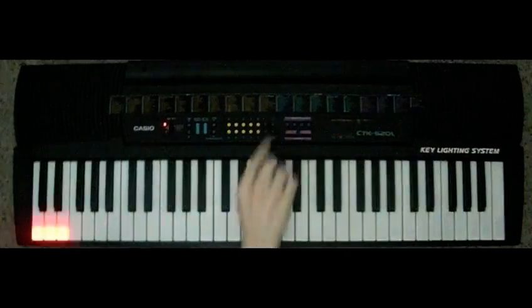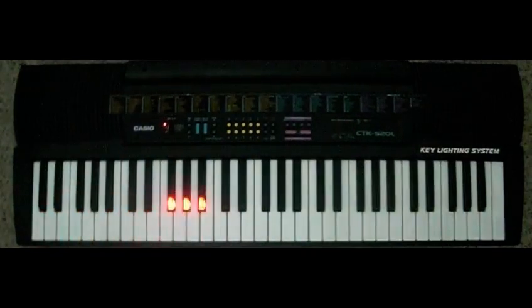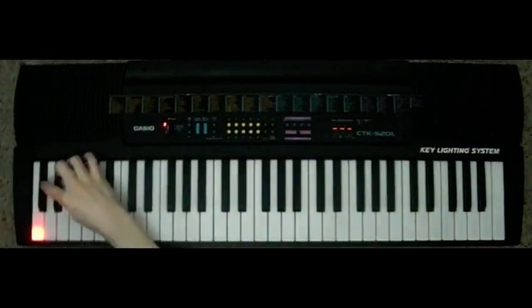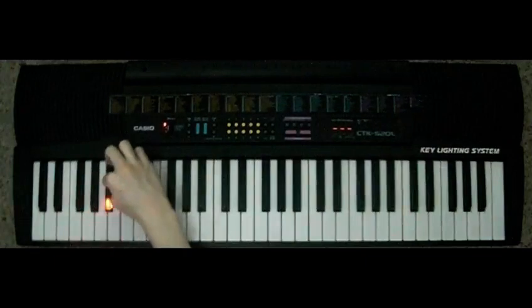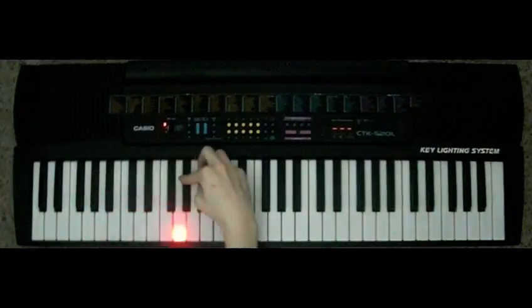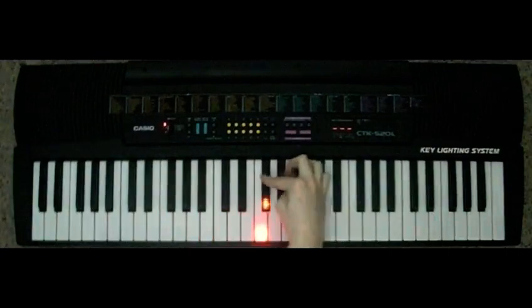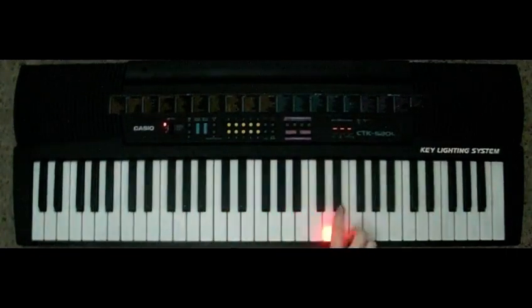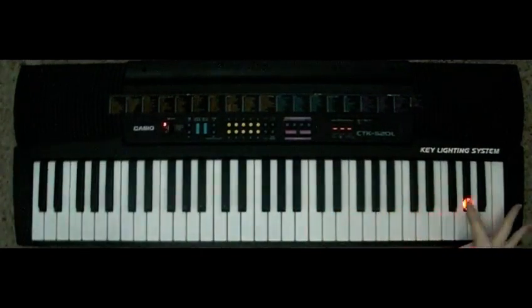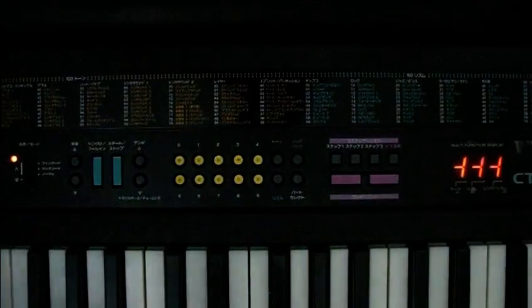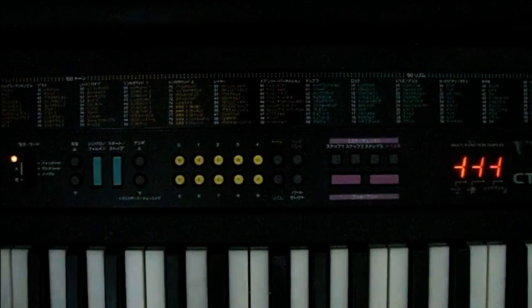To test the LEDs, press tone. To test the keys, press rhythm and then press each key. To test the AC adapter detection test, make sure that there are good batteries installed in the unit, then unplug the DC jack from the back of the unit.